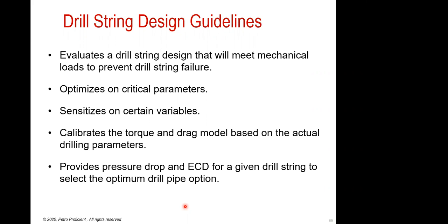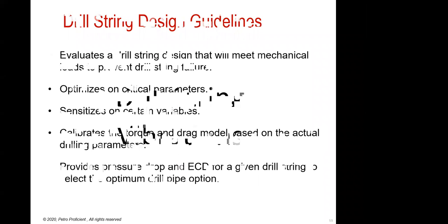If you have a very small drill string, the pressure drops are high. If you have a big, wider drill string with big tool joints, then pressure drop in the annulus is high. Considering all this, you need to balance your design very well to make sure that it satisfies all the requirements and you are not taking unnecessary risk. These are parameters associated with drill string design.